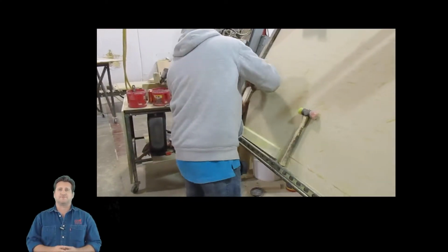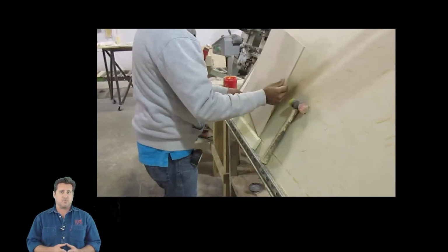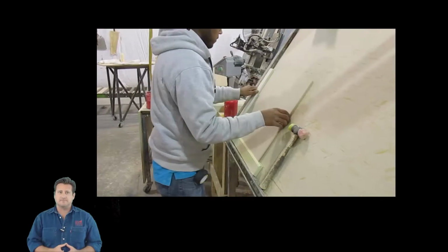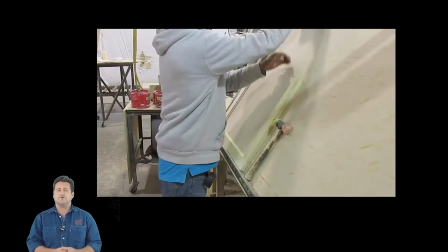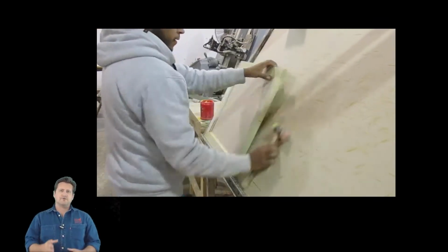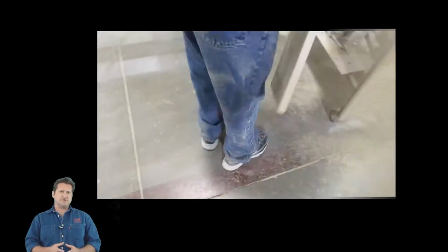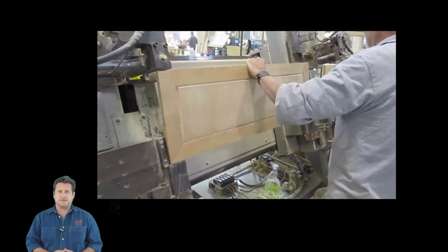First, the coped ends of the rails are painted with high-strength wood glue. Next, the rail, with glue applied, is inserted into the end of one stile. Now the inset panel is inserted into the groove of the stile and rail. Then the remaining rail and stile are loosely joined together, as is being shown. The shaker door is now roughly assembled and ready to move to the clamping station.